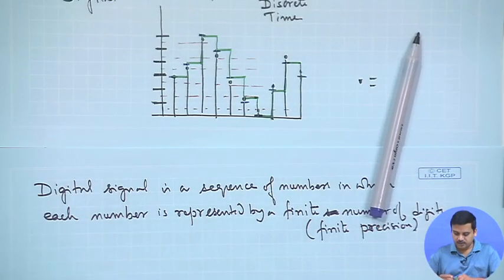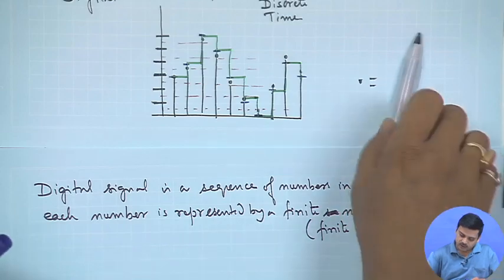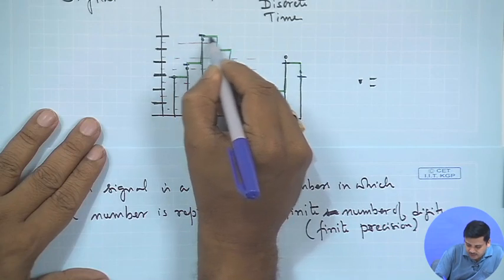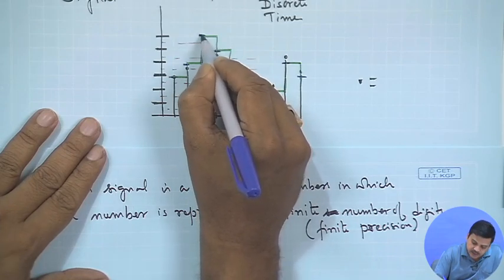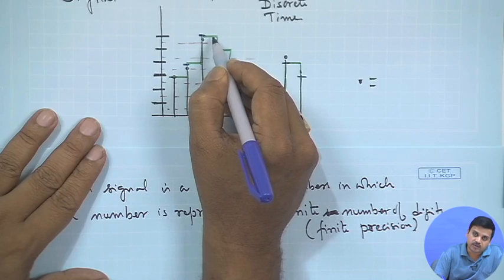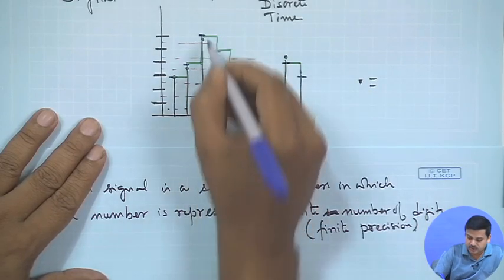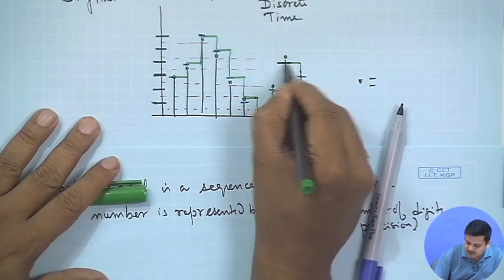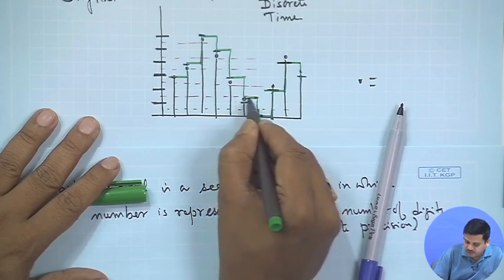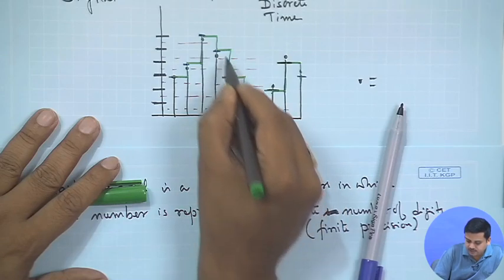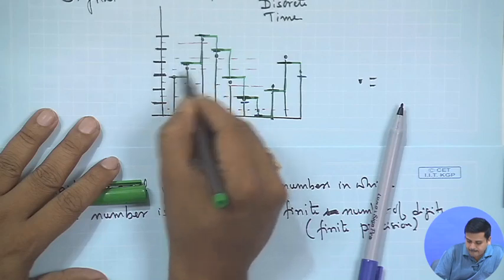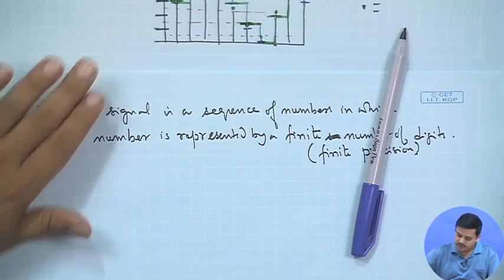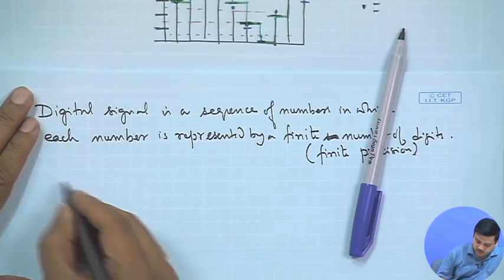So, this is how the signal might look once you have converted to a sequence which is mapping to a particular level. Basically, why I have drawn this, I have simply indicated that this value is held for this time. So, one can reconstruct the analog signal in this way. So, rather actually what we mean is that we have conformed to this level, we have conformed to this level, we have conformed to this particular level, right. So, that is how it would look like, and this particular process is known as quantization,